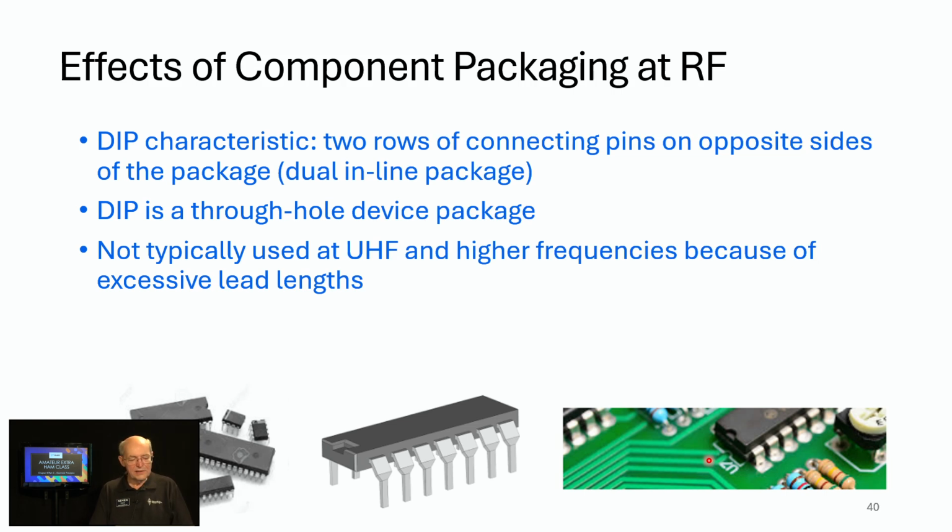They're not typically used at the really high frequencies, UHF and above, because of excessive lead length. You're probably looking at this and saying, these don't look like very long lead lengths. But when you get into UHF and above, up toward microwave frequencies, these lead lengths do become very significant. So they don't use these parts there. You can see we've got 3 easy pool questions about this.